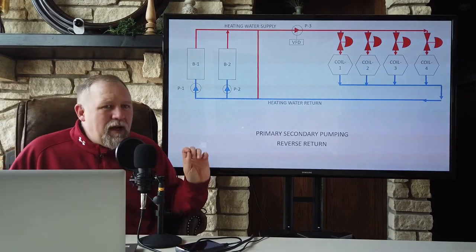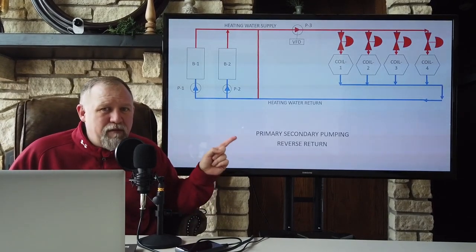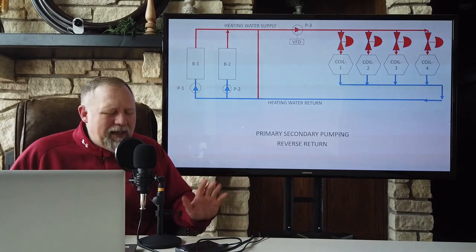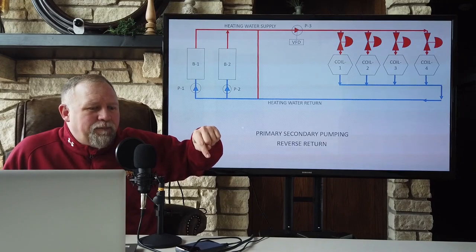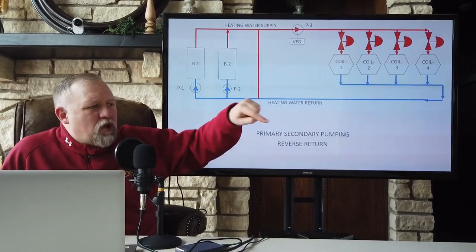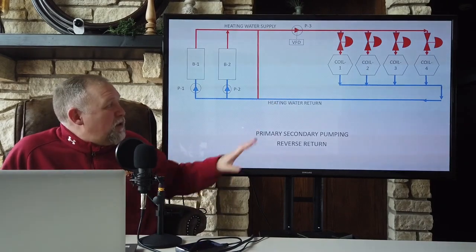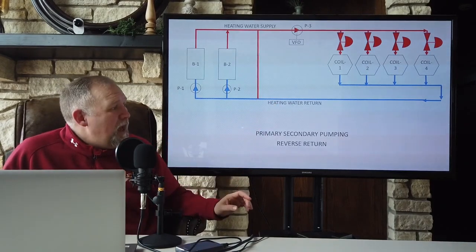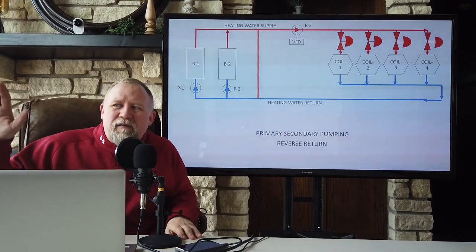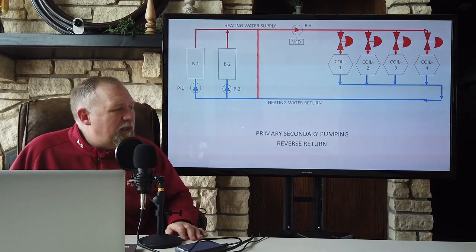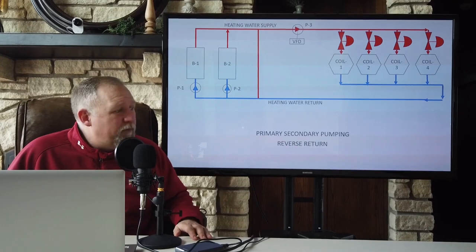However, depending on the layout of your building, this might result in more total length of pipe. Maybe. It depends on your building. If your building is like in the shape of a circle or a square, in other words, it naturally lends itself to a loop, this might not add any piping. However, if you have long branches or wings of a bunch of individual parts of the building, this could end up being very difficult to do. It might not be practical for every loop.